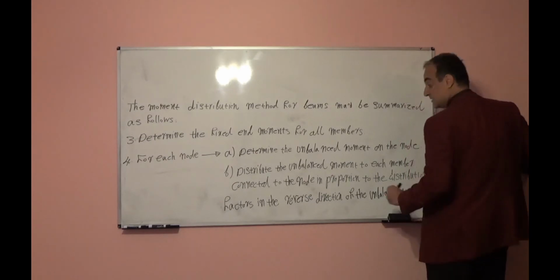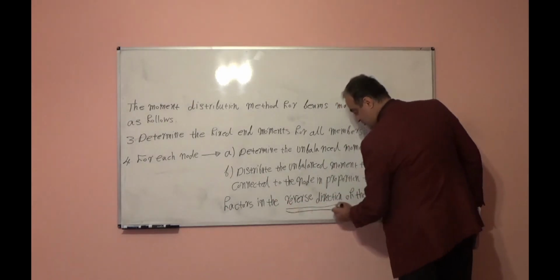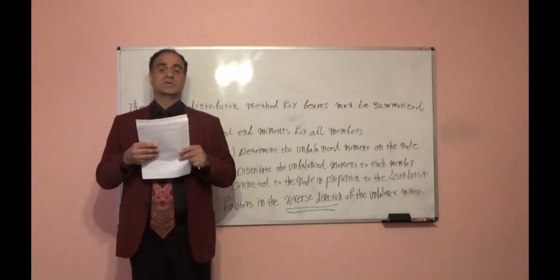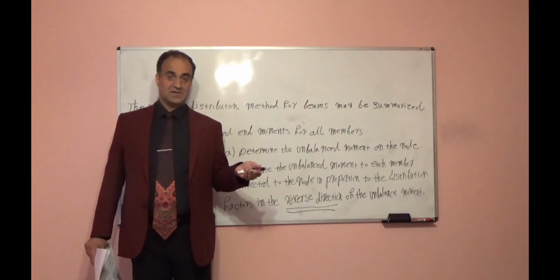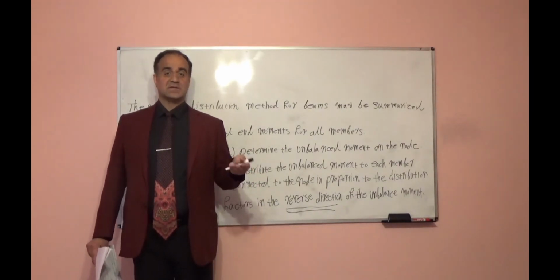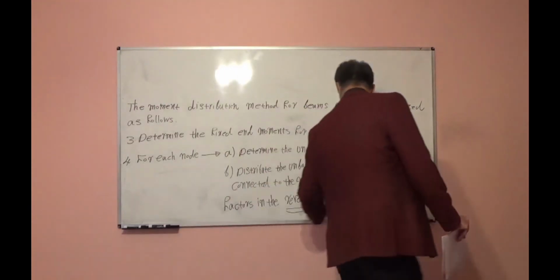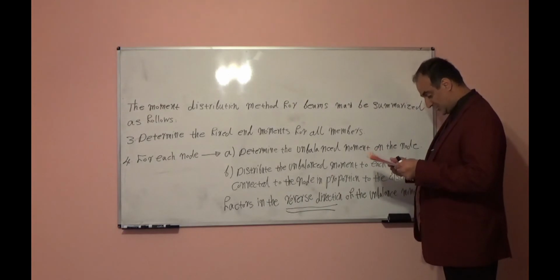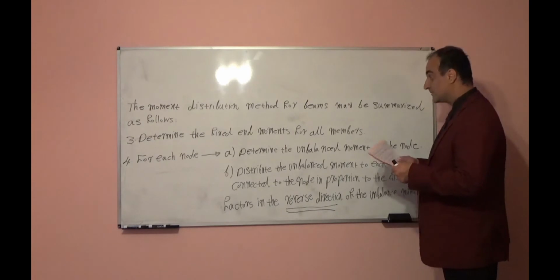Pay attention, in the reverse direction, this is important. If the resultant unbalanced moment is clockwise, you will distribute counterclockwise. If the resultant unbalanced moment is counterclockwise, you will distribute in clockwise direction. Later on I will explain the concept, you will see why.